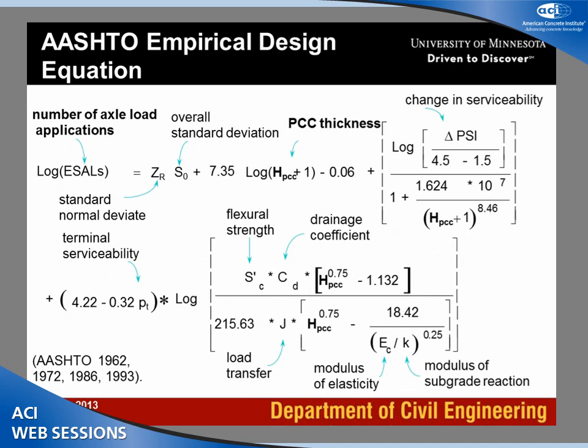Well, again, it's a purely empirical equation. Basically, even these parameters are indexes and cannot really be improved. And it caused very thick pavements for high traffic on the interstate highway. So this is why AASHTO and NCHRP decided to develop a mechanistic empirical design guide.